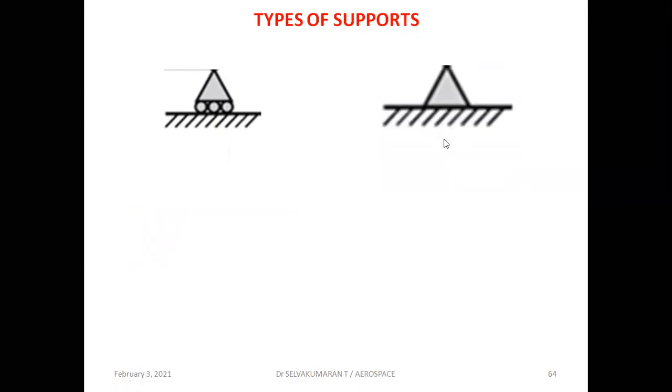Next, this is the hinge support, where you will have one vertical and one horizontal reaction. For example, if R is the unknown support reaction at point A, I call the vertical one RAV, for example. Now the horizontal one, at A, is acting horizontally.